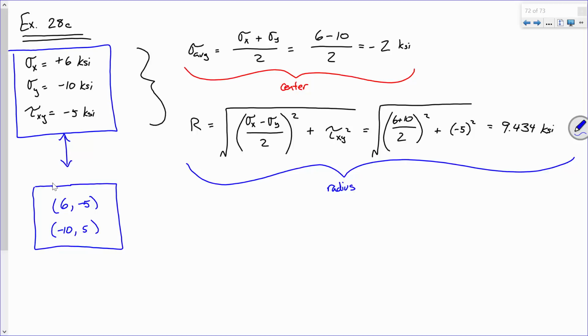Well, as long as you're keeping track of your signs, yes, you are right. But that's sort of where, like if you've got a beam that has multiple point loads on it, right? Each one of those point loads is going to generate different shear stresses, or different shears. But that's where a shear diagram comes into play. When you draw a shear diagram, you are taking into account your sign conventions, because you're either going up or going down. But when you're in design mode, you just look at that shear diagram and say, okay, what's the worst case magnitude? And that's the one you're going to use for design. Whether or not that magnitude is a positive 2,000 pounds or a negative 4,000 pounds, you're just going to go with the 4,000, because magnitude doesn't matter. In that instance, we're talking about either doing that or doing that, and it doesn't matter.